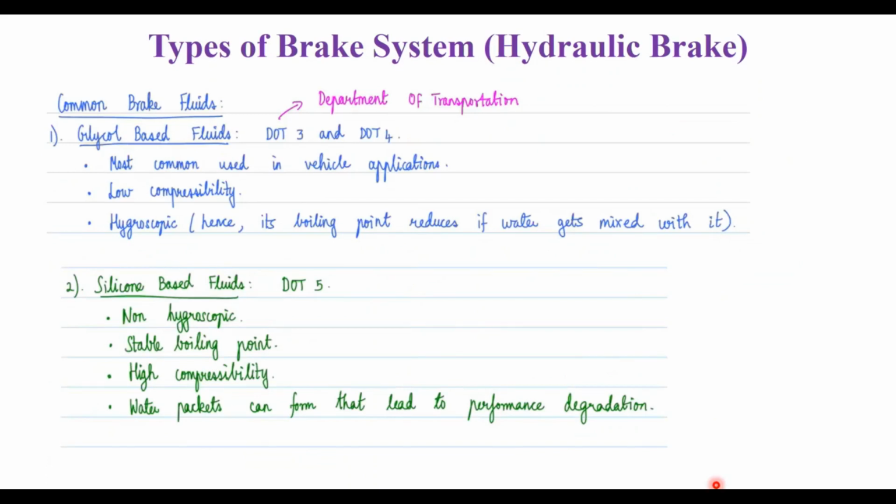And Department of Transportation is called DOT. They have prescribed the common brake fluids that can be used, which are glycol-based fluids, called DOT 3 or DOT 4. It's mostly used in vehicle applications, having low compressibility. Its boiling point reduces if water gets mixed with it. It's called hygroscopy.